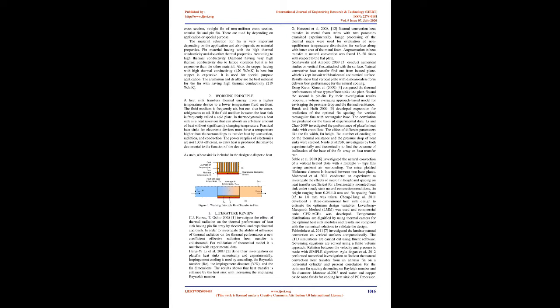2. Working principle. A heatsink transfers thermal energy from a higher temperature device to a lower temperature fluid medium. The fluid medium is frequently air, but can also be water, refrigerants, or oil. If the fluid medium is water, the heatsink is frequently called a cold plate. In thermodynamics, a heatsink is a heat reservoir that can absorb an arbitrary amount of heat without significantly changing temperature.